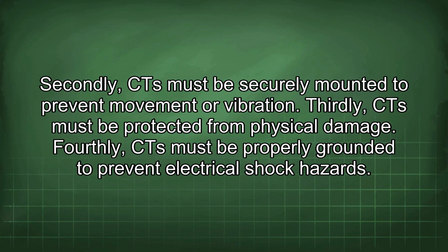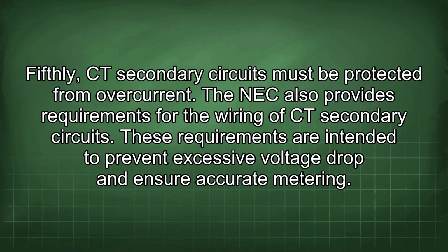Fourthly, CT must be properly grounded to prevent electrical shock hazards. Fifthly, CT secondary circuits must be protected from overcurrent. The NEC also provides requirements for the wiring of CT secondary circuits. These requirements are intended to prevent excessive voltage drop and ensure accurate metering.